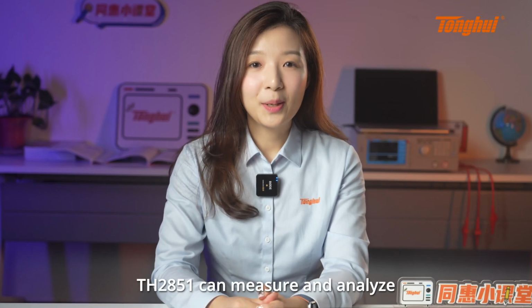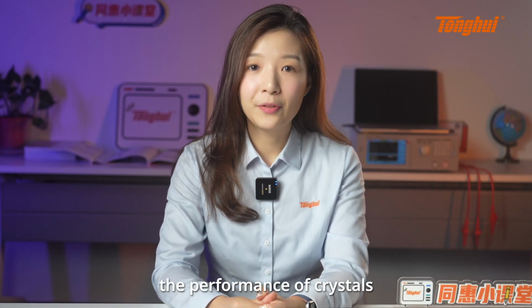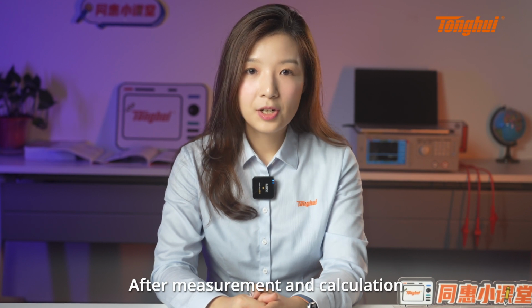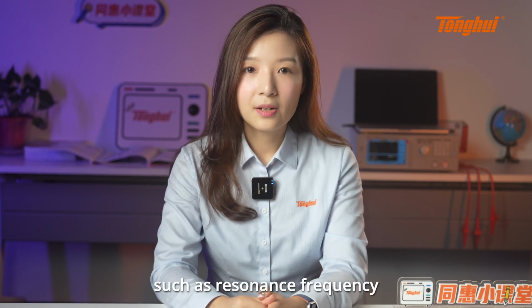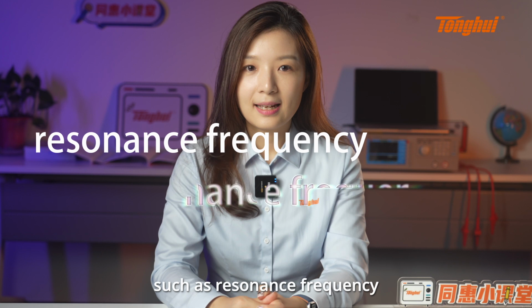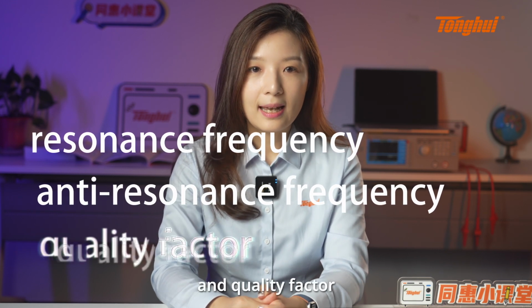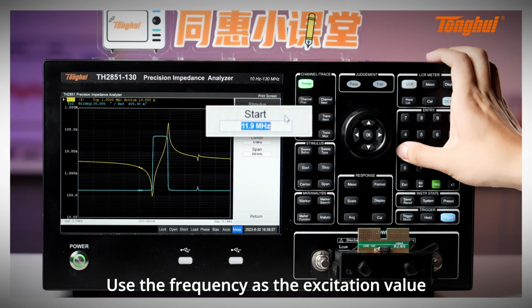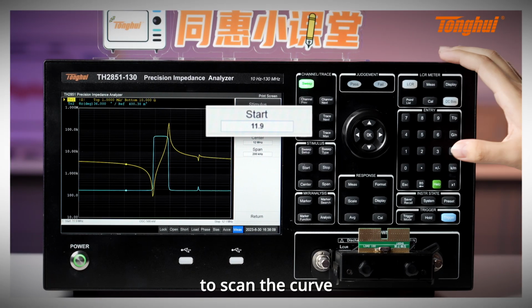Crystal Oscillator Analysis. TH2851 can measure and analyze the performance of crystals such as piezoelectric ceramics. After measurement and calculation, important parameters such as resonance frequency, anti-resonance frequency, and quality factor of the crystal can be obtained. Use the frequency as the exciting value to scan the curve.